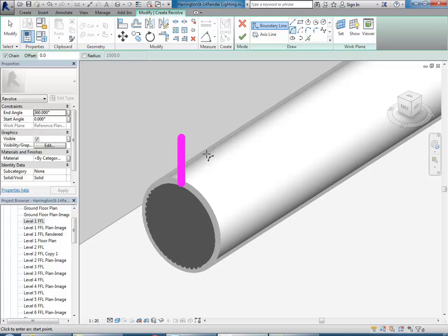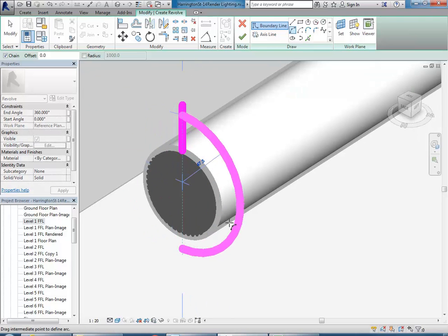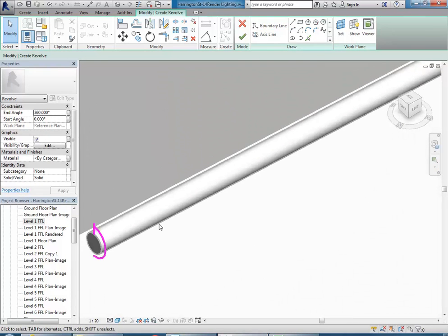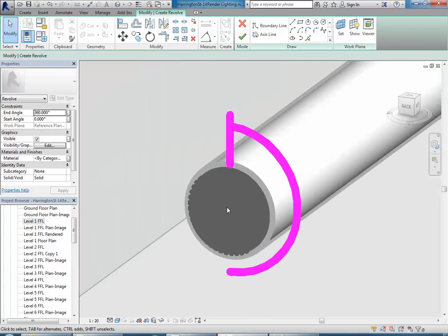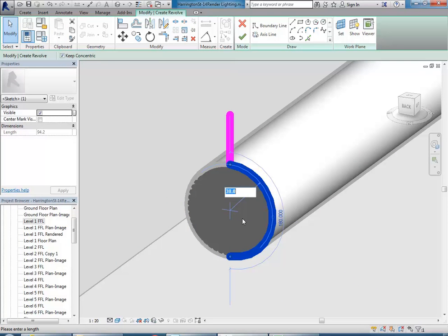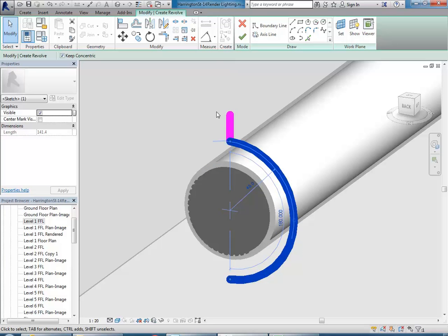And so then I'm going to draw an arc that comes down and is basically going to be parallel with my curve. Now I've made that one a bit big, so I'll just draw that again, and I'll use pick lines just to show you a trick there. If you use pick lines, you can pick an existing curve. Yeah, so I could have offset it as I make it, or after you've made it you can easily just change that. And 45 maybe.